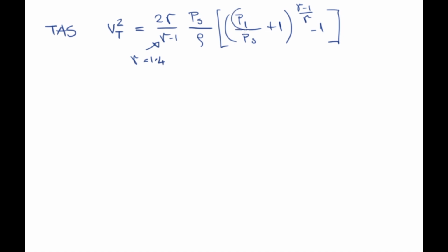It's just a pressure gauge that displays this impact pressure, and the airspeed indicator is calibrated in units of speed, simply because units of pressure are not particularly intuitive when we want to pilot an aeroplane. So what we have displayed on the airspeed indicator, on a simple mechanical airspeed indicator, is the indicated airspeed.